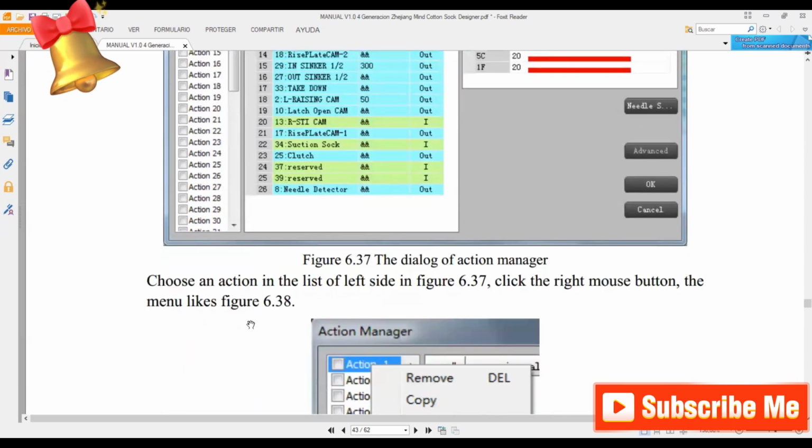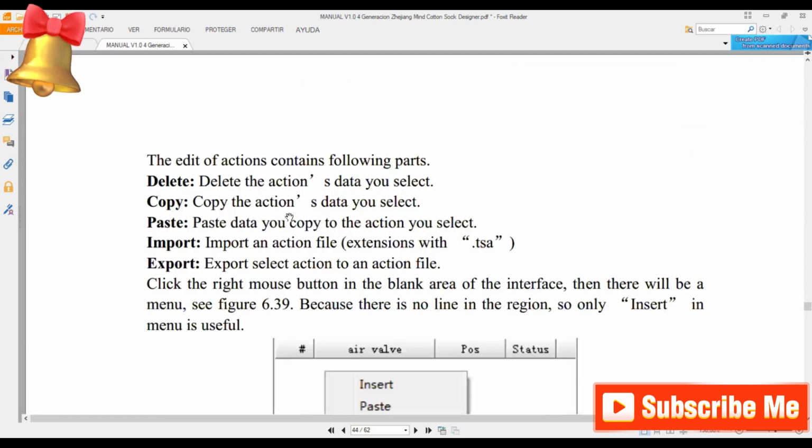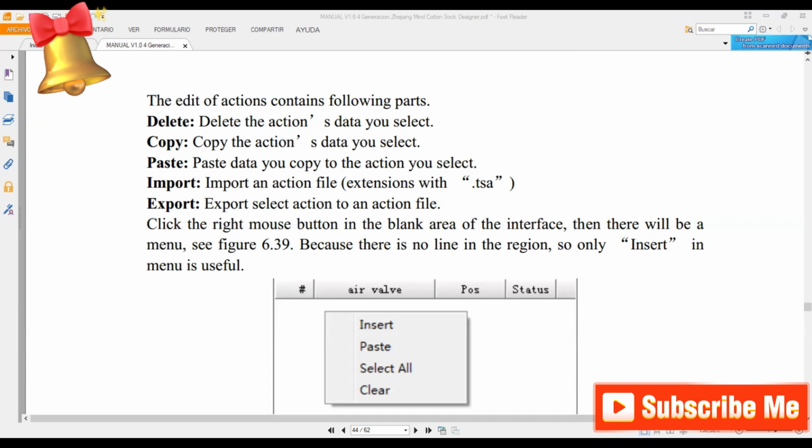Choose an action in the list on the left side in Figure 6.37. Click the right mouse button. The menu looks like Figure 6.38. Figure 6.38 Edit of Actions. The edit of actions contains the following parts. Delete the action data you select. Copy the action data you select. Paste data you copied to the action you select. Import an action file, with extension .tsa, and export the selected action to an action file.